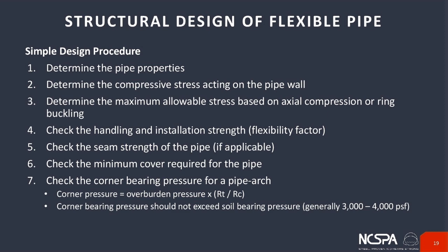If it's a riveted pipe, you'll have to check the seam strength on it. You do a quick check for the minimum cover that's required. And then if it's a pipe arch, you need to look at the bearing pressures on the corners.